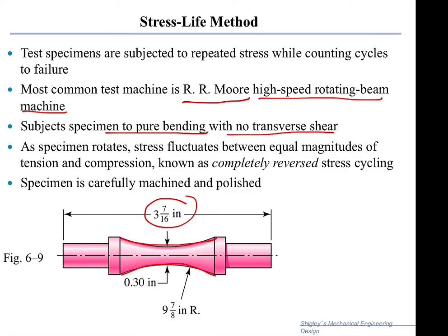So we know that if we have failure, it is going to be in the middle section, and the sample is rotated, like here, and while it's rotating, we can load up the two sides, let's say a load P here and a load P here, while it is supported on the ends. So we have two supports and two loads.